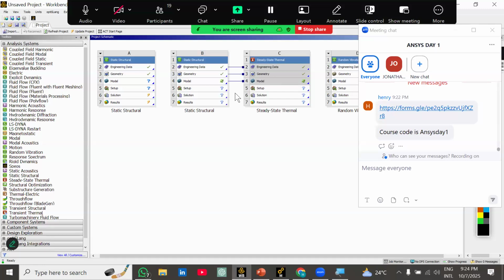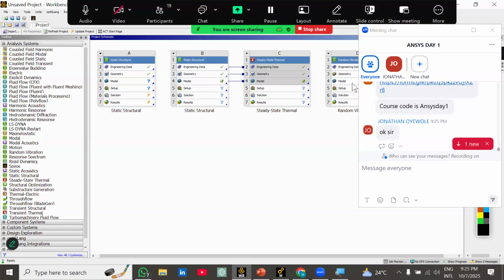You can open any CAD file in Fusion, and in Ansys here too. It doesn't necessarily have to be a step file. But if you're having any challenge opening a file, I advise you, step files are the generally accepted file format for any engineering software.